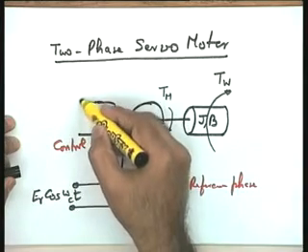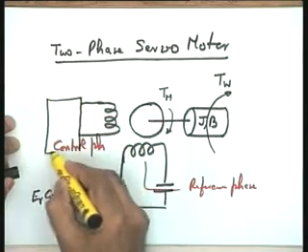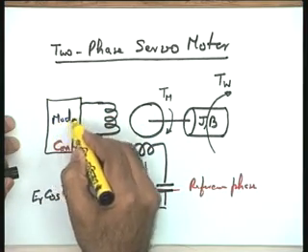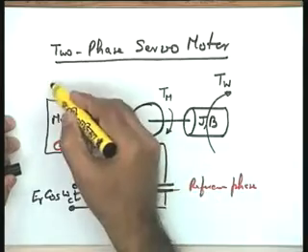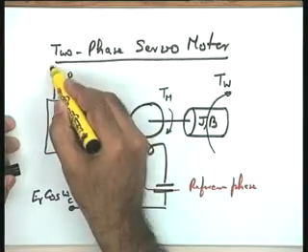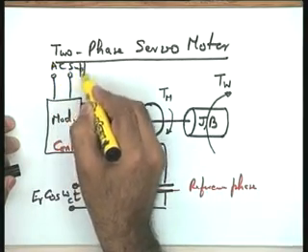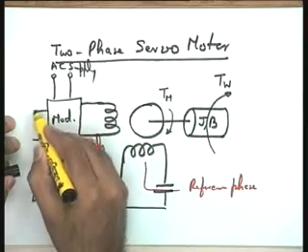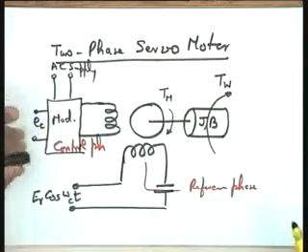For reasons to be made clear shortly, I put a modulator here, and this is the AC supply here. And what is the input to the modulator? The input to the modulator is the control voltage EC. I need your attention here: the input is control voltage EC, which is always in a control system a low frequency voltage. Recall the specific objective of EC. What is EC? EC is an error signal.